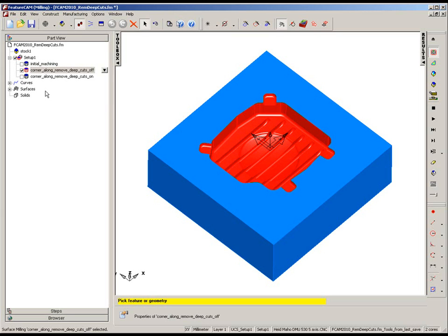In the case of this example, we have the first option here, corner remachining with remove deep cuts, switched off. So let's just simulate this in centerline. You see we get the machining of the inverted ribs, there's the corner tabs, and the final circular section on the inside. So let's zoom into one of these regions here.